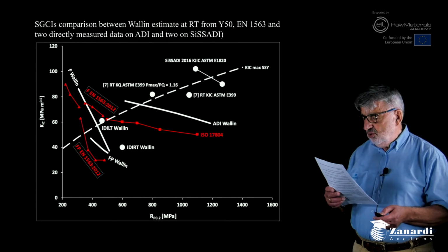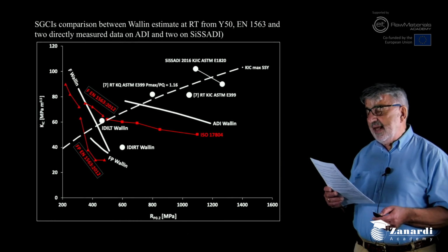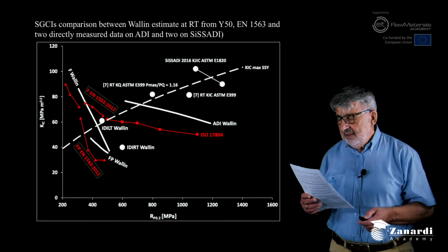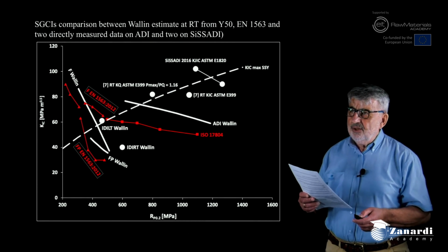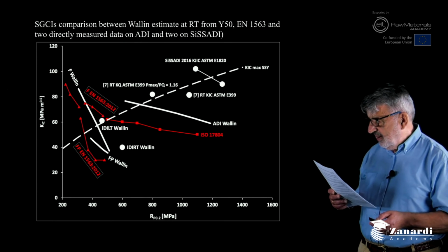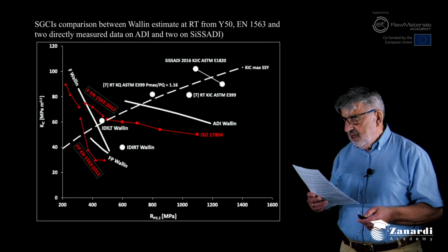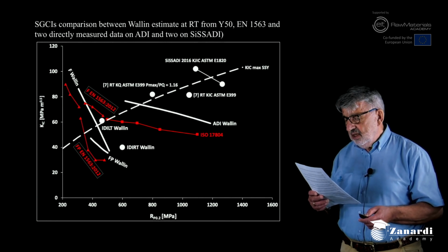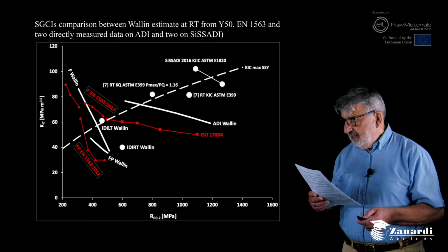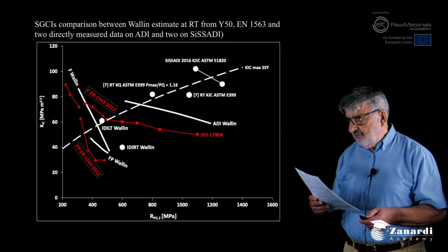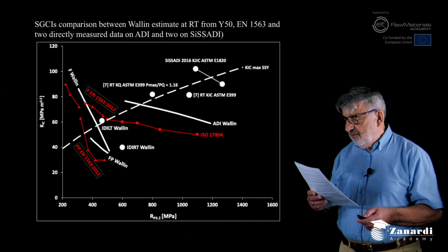Discrepancies between the two sources exist for silicon solid solution strengthening, the so-called high silicon ductile irons. Following Wallin, that is driven by the Charpy V-notch, the dependence of K1C on silicon content and Rp0.2 is stronger. Probably it is an effect of the strain rate that needs to be distinguished from the static fracture toughness. The same approach needs to be adopted for IDI.